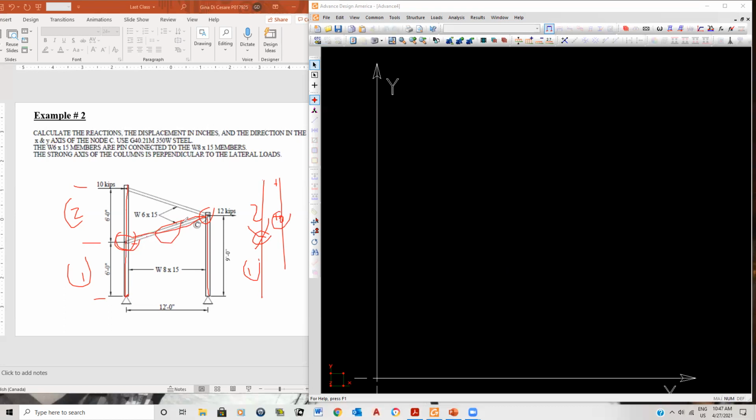And then on top of that, these diagonal members are pin connected to these members. They're not fixed. If they are fixed, then you can model them as being fixed. And by default, when you add this member, the program will fix this member to that member, and we'll have to go and release it, just like we did for the beams, for the smooth pins. That's just to give you an overview of what we're doing.